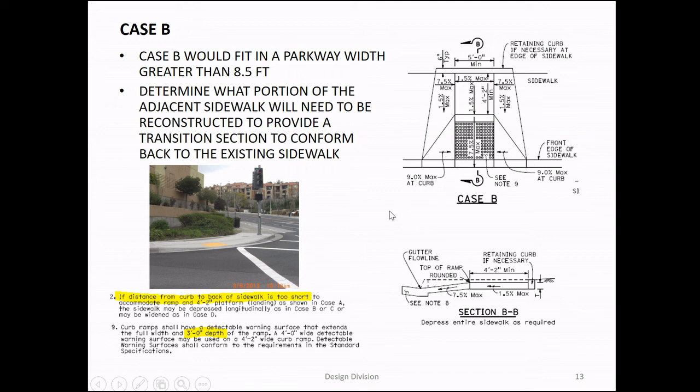Oh, one thing I forgot, because these things are being scrutinized so closely now, is that we are going to make sure that this here, which is the curb ramp, meets this standard. So if you're not reconstructing the sidewalk, and for sure the sidewalk is not going to meet this standard, we should add like a 2-foot strip on each side of the ramps to join existing.